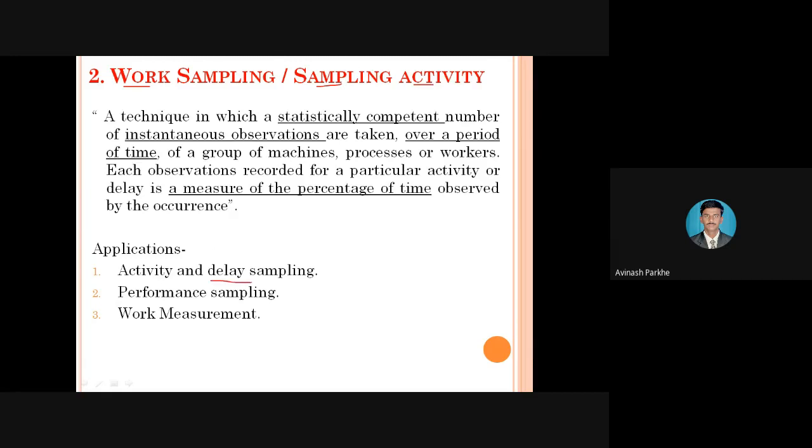And delay sampling: whenever operators are performing a number of operations, due to some unavoidable activities, maybe the breakage of the tool, breakage of the oil, finishing of the oil, finishing of the coolant, like that so many unavoidable activities are generated. At that time the delay takes place in that particular operation. How much delay is taking place is also observed by the supervisor. Therefore, whatever activities we are performing, and the delays obtained during those activities, are also calculated by using this work sampling.